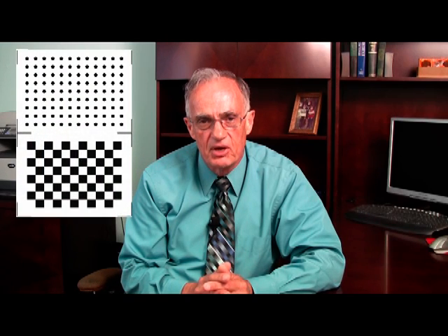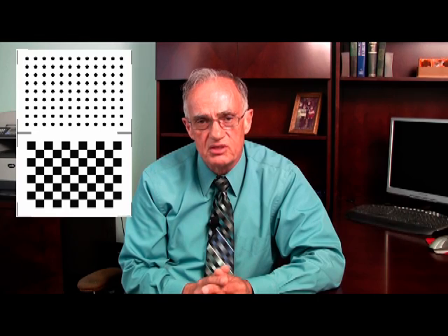While there are machine vision applications that aren't affected by optical distortion, vision systems that make measurements are affected by optical distortion. Distortion may be caused by the lens itself, and it may be caused by the camera not pointing perpendicular to the field of view. Vision systems that do make measurements often or usually provide for the correction of distortion by using a target that commonly consists of an array of dots, or in some cases a checkerboard pattern. Follow these steps to calculate your lens's distortion.